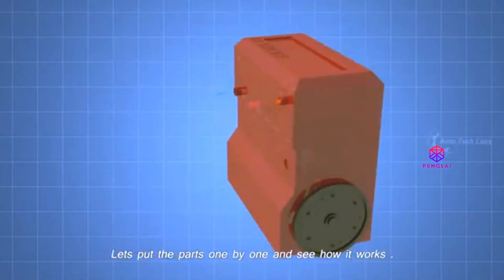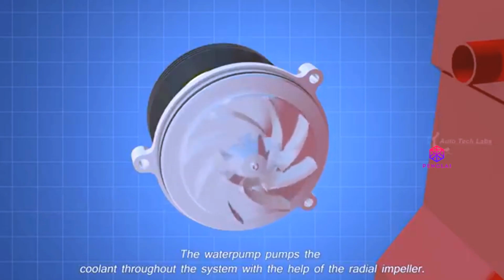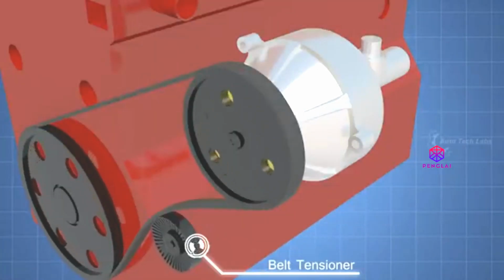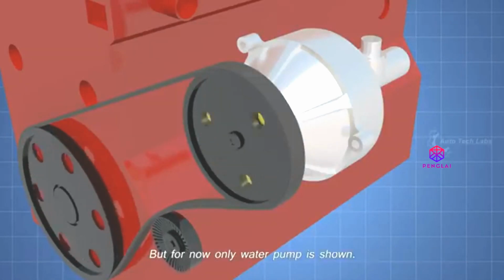Let's put the parts one by one, and see how it works. The water pump pumps the coolant throughout the system with the help of the radial impeller. It is driven by the engine itself, using a serpentine belt. The serpentine belt also drives the power steering pump, alternator, AC compressor. But for now only water pump is shown.